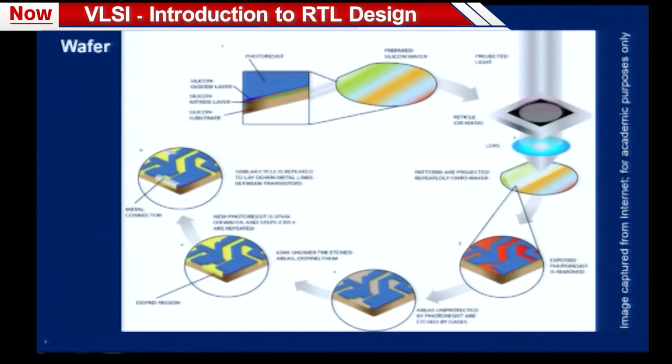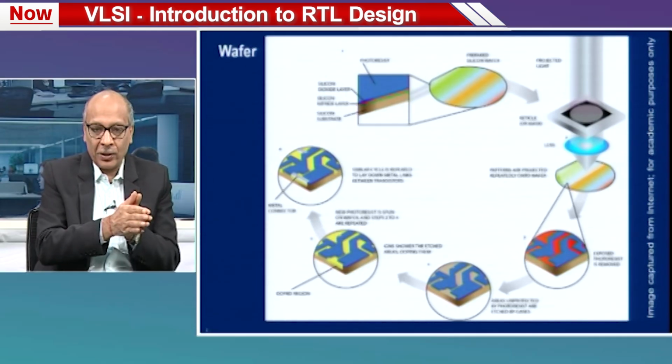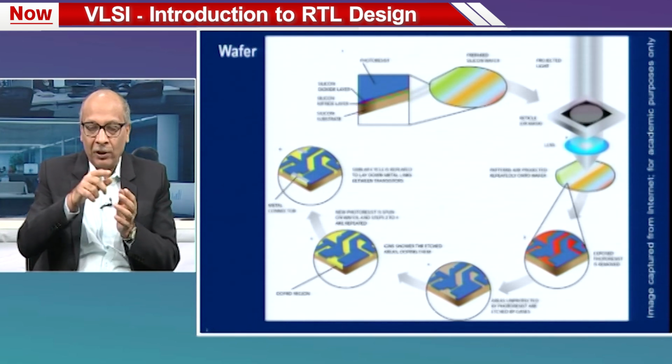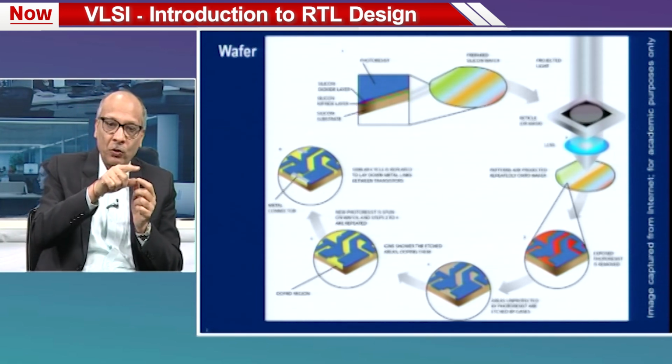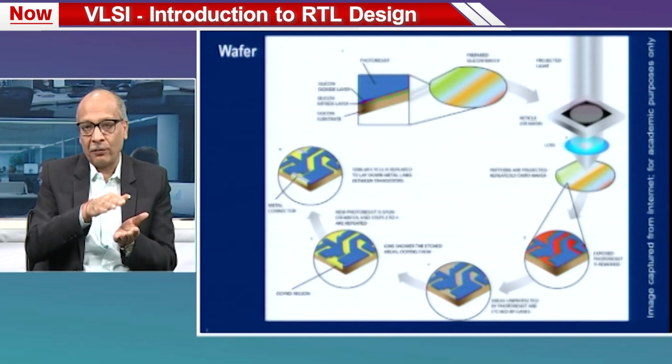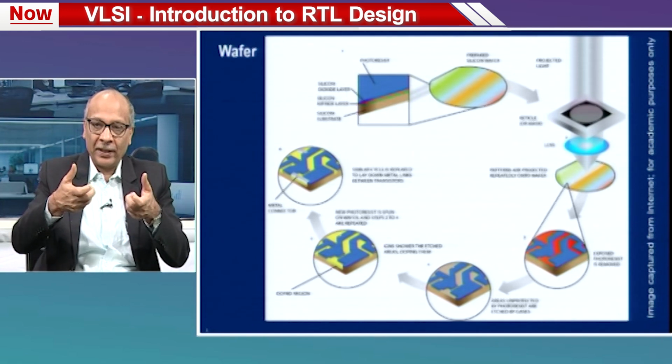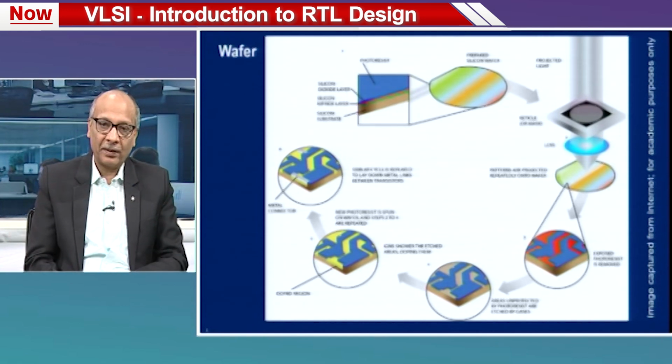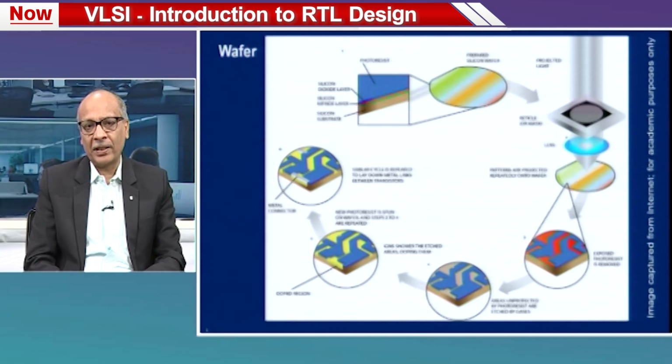So, effectively after the doping, you have some transistor layers created. The photoresist prevented the doping at some places, at other places doping happened, and we will keep doing this multiple times to establish the metal connections and so on. Through multiple layers of etching, doping, etc., we would finally get the semiconductor wafer done. This kind of work happens in companies like, say, TSMC.